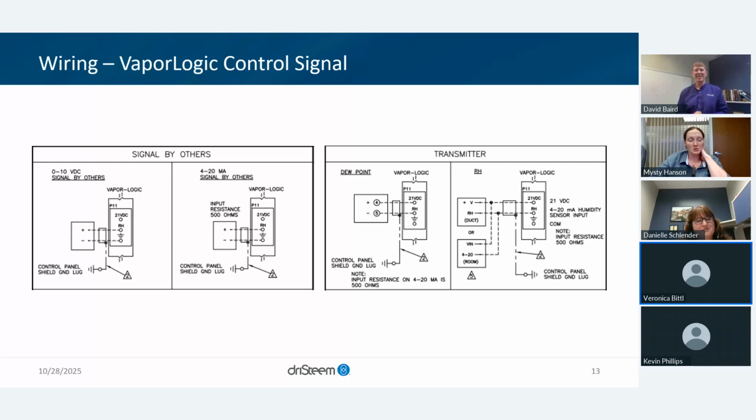So this comes up quite a bit when my contractors go to install. They're like, this humidity transmitter and the high limit humidistat, isn't that the same thing? There's always some confusion. And then the question that follows is, what is the generator going to control to? Is it going to be the humidity transmitter, or is it going to be the high limit humidistat? They hear stat and they think that's what's dictating things. So how would you dumb it down to communicate it?